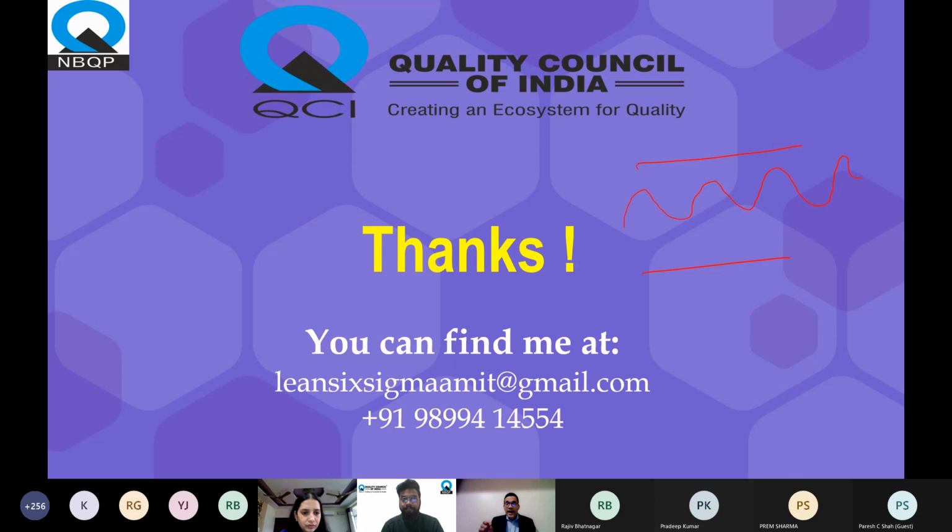is robust enough, but I am getting this OD problem in my pen or in my piece. Then I have to do root cause analysis, apply lean methodology, lean tools, brainstorming, Pareto, all these things, to drill down: if this is the problem, what is the root cause? How to cut it? So MSA is just going to give me the clarity whether the operator and the gauge which I am using are good enough or not, whether I can continue with this or not. The problems which are falling is not part of MSA. It's part of some root cause analysis tools and all those things. So this will be a different ball game altogether. So MSA talks about this only.